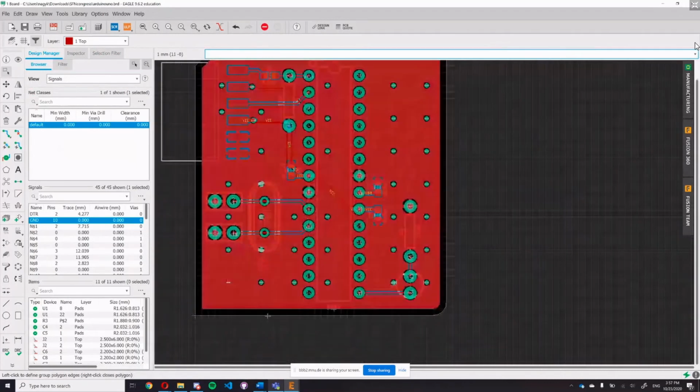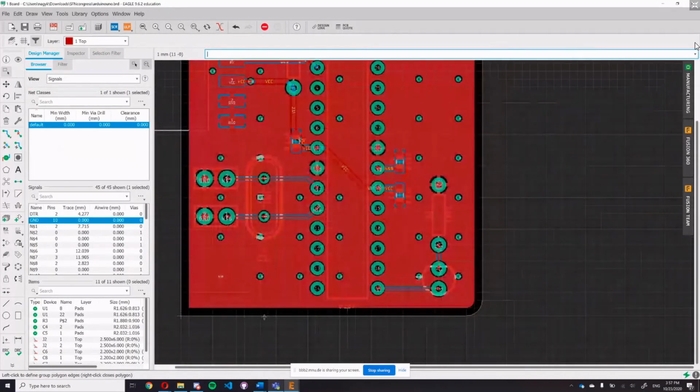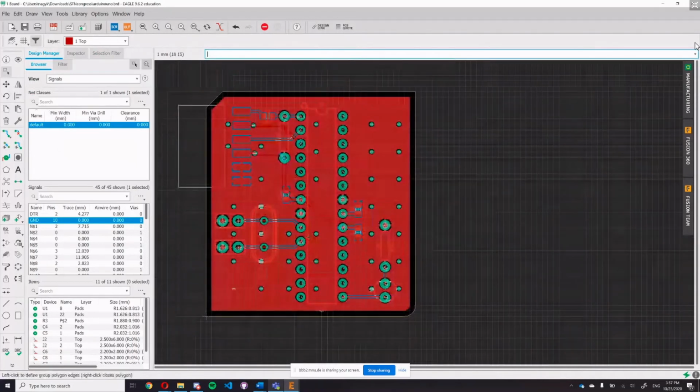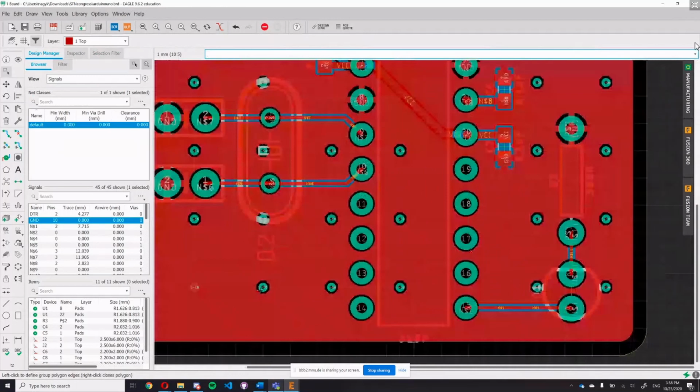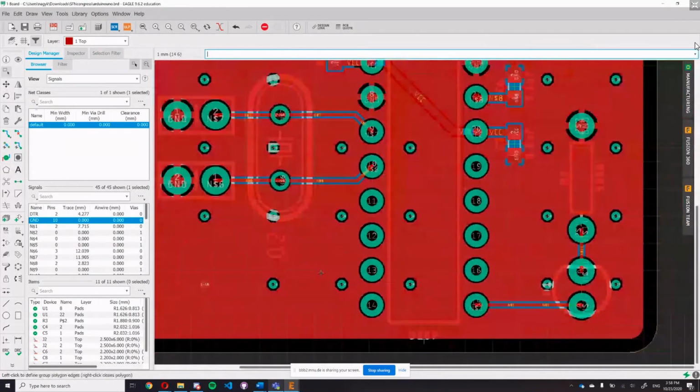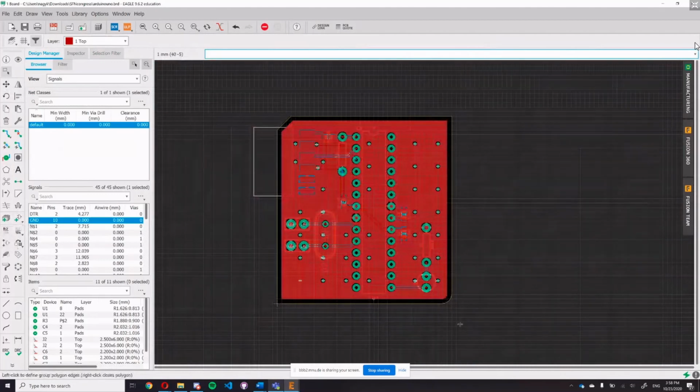I don't know if that's possible in Eagle, if you place a via and rename it to GND, and then you place many vias, I think they all share the same name. Or you could use the group tool and control click every via if needed.